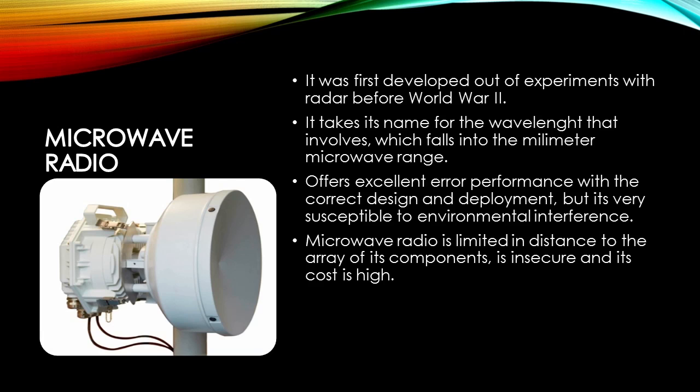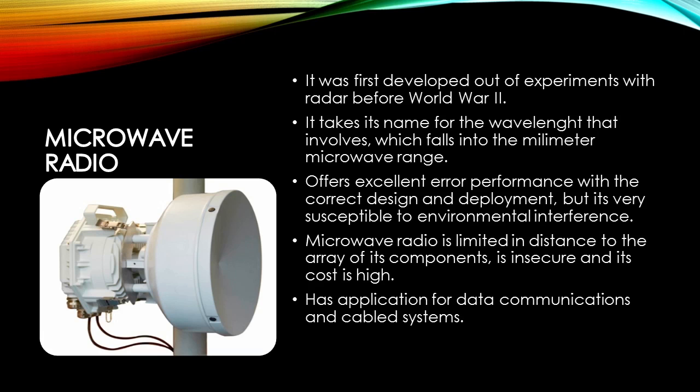This could be mitigated through a larger antenna and antenna arrays incorporating spatial density and frequency diversity to increase the quality of a collected signal. Some of their disadvantages are that they are really insecure networks and the acquisition, deployment, and rearrangement costs can be high. Microwaves have been used extensively for long-haul voice and data communications. They are also preferred for cable systems due to their relatively high speed and low cost of deployment.